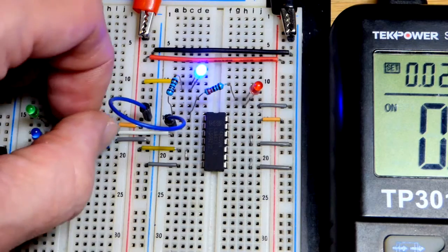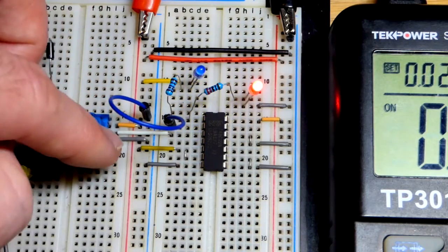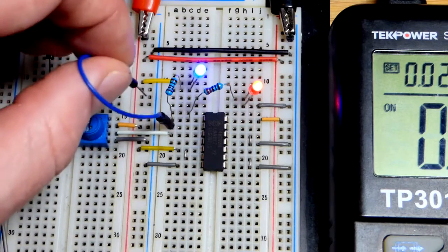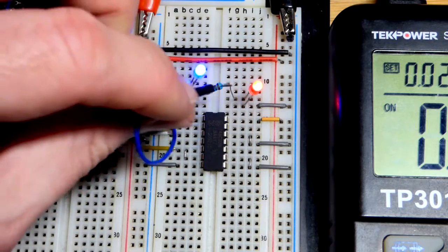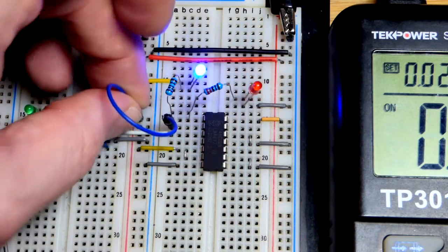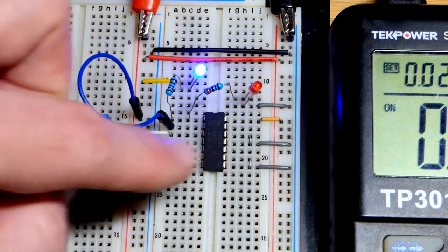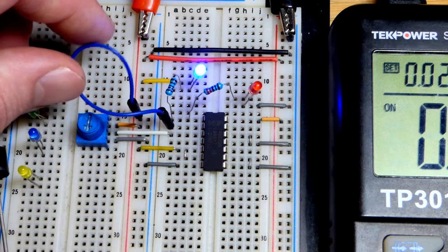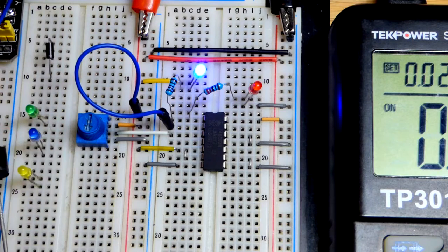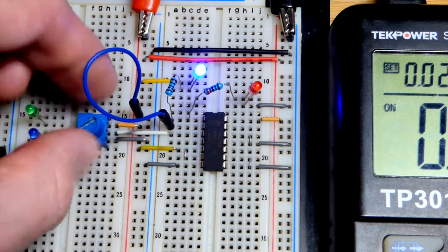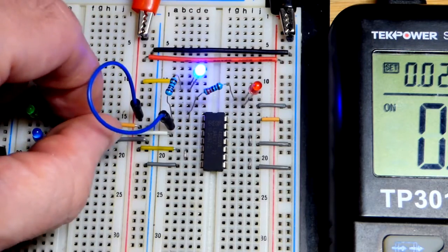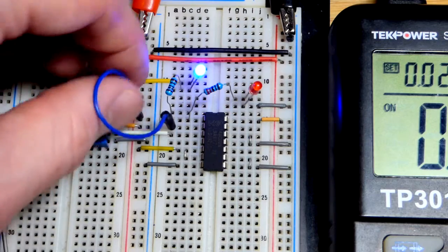And so we got them both low. But if that one goes low and that one's low, we got the output high. And then if we get the output high, see, this is why you don't leave inputs floating. It makes the output erratic. It'll probably bounce back and forth between two states. So that's why all these other inputs are tied to a power supply rail. Now we have a positive there, but low down here. So it doesn't matter what we do now with this one. We have a high input, so the output's going to be low no matter what, whether or not the other input is high or low.